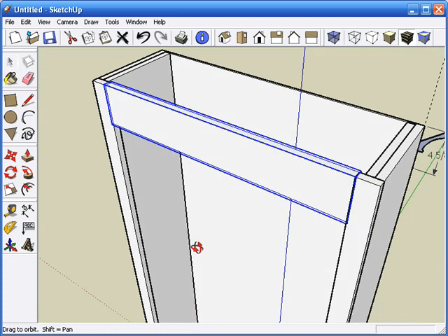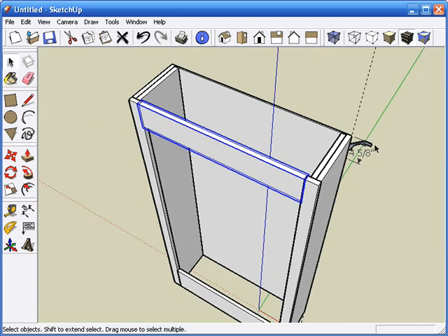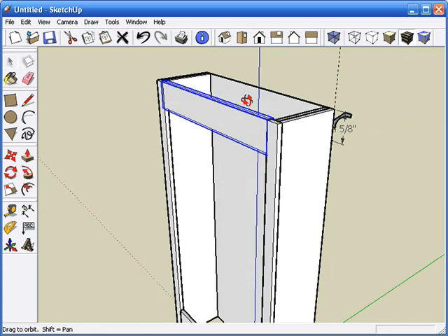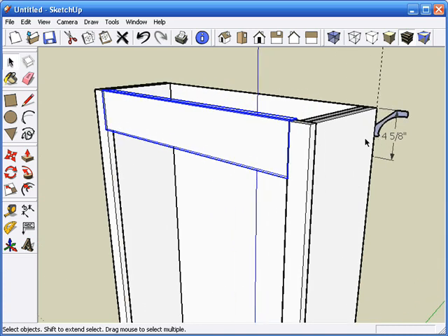I like to run the crown before I put a top on it, because that way you know how big to make the top. It's a lot easier. And I really do the same thing when I'm building a bookcase. But instead of just running the crown straight around this thing, I like to dress up the fronts of my bookcases. So let's do a little Gothic thing here, kind of a little Victorian thing. We'll build a little box right here, and let's bring it down so it comes down right to the bottom of that lock rail, just like so.